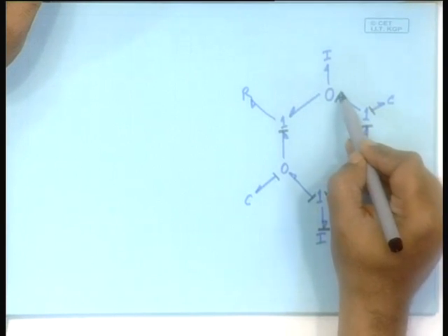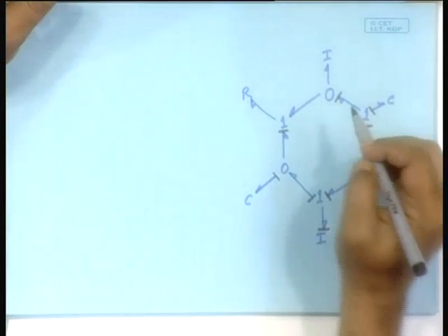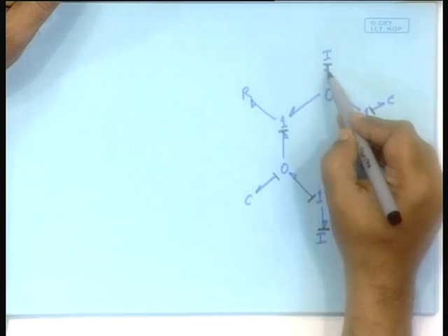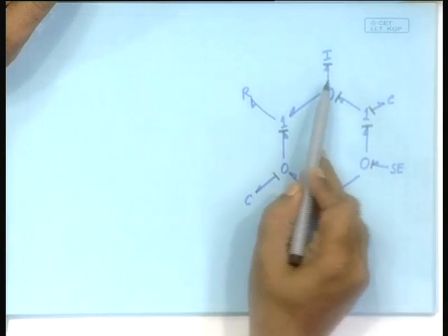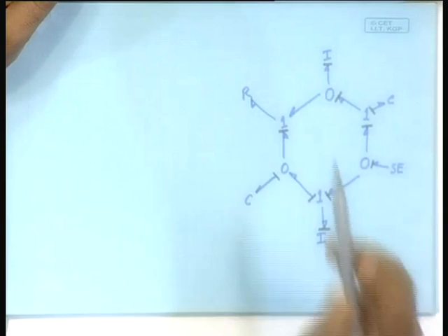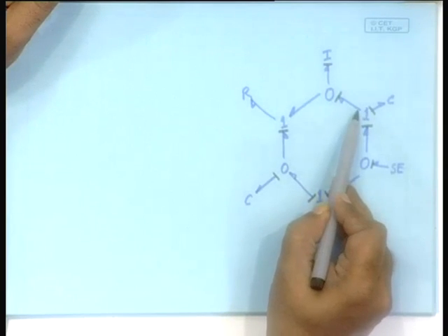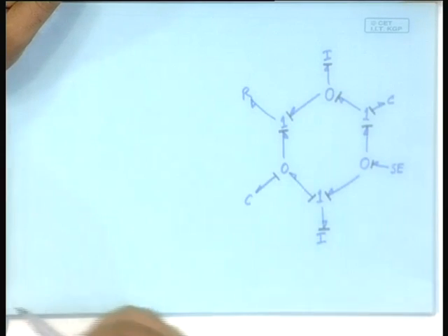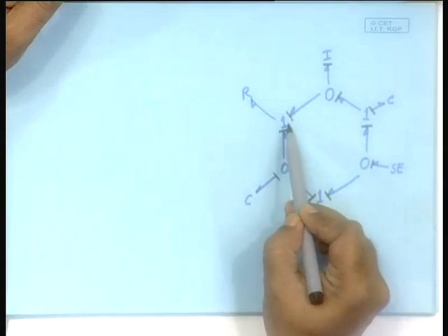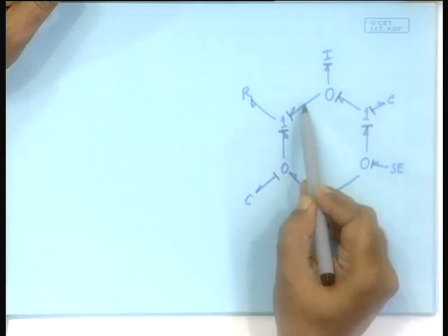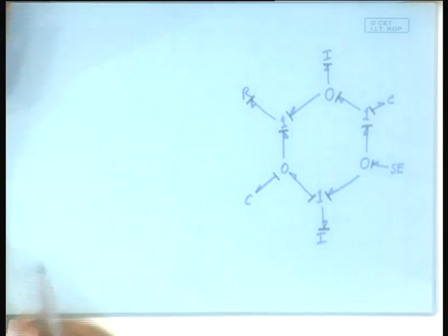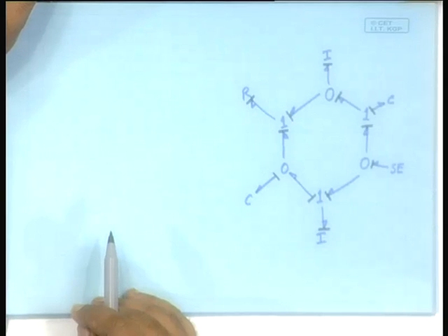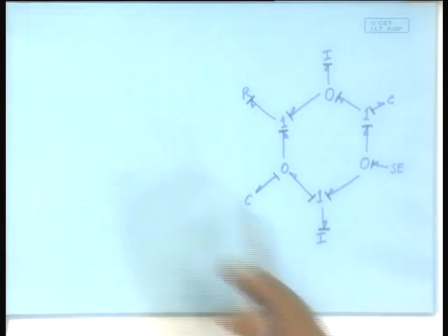So, in this 0 junction, as yet the causal structure is not complete. So, we will put it here. This is the natural causality of the I element. So, it has taken out the effort information, this one has brought in the effort information, 0 junction. So, this has to take out the effort information. 1 junction, both these are taking out the flow information, and therefore, this fellow must be giving the flow information. Okay? Then it is done. Okay? So, that is the causal structure, and then you put the numbers.